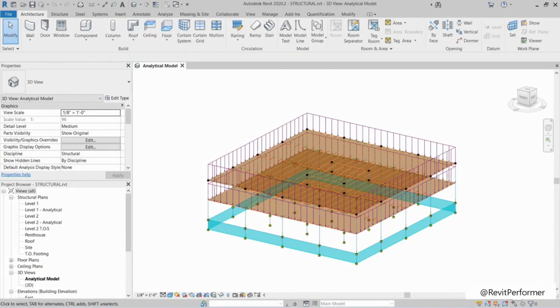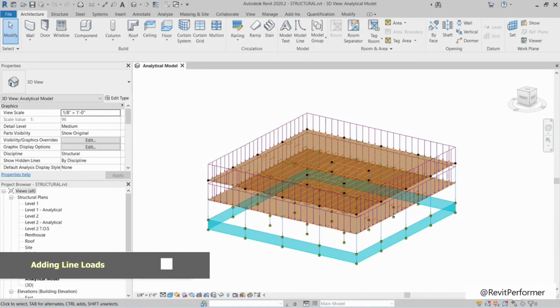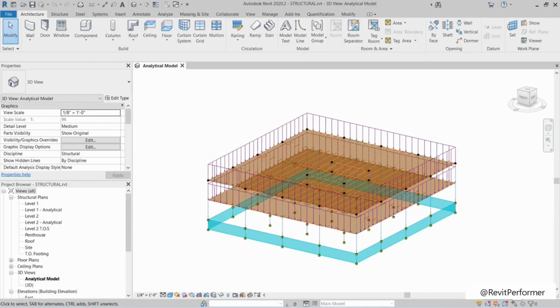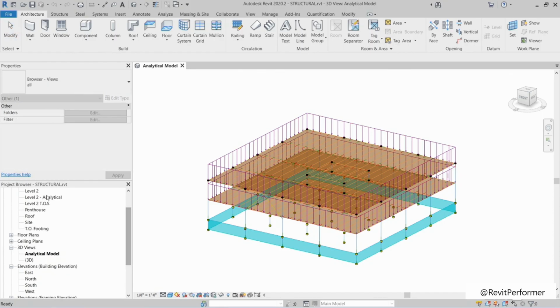Another short. Let's place a load that is basically line-based. We do this by using a similar methodology as we do when we place basic components into our model. In this video, I'd like to place that AHU load we made into our model. Let's jump into Revit. In the project browser, let's scroll down where it says Penthouse. Let's open that up.